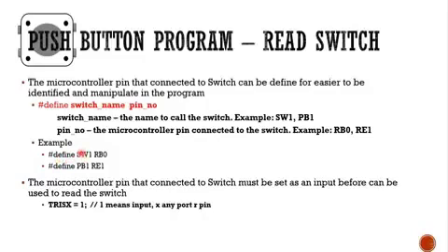It is not necessary to use SW1. Okay, you can put switch 1, or SWITCH, you can put the full name, you can put just an abbreviation, okay, just as long as the programmer understands. Okay, so for this one, we could define SW1 at RB0, then PV1 at RE1. So this means that after this, when we want to refer to RB0, we just call up SW1. But first, we need to set RB0 and RE1 since we are reading. We need to set the respective ports here as input.